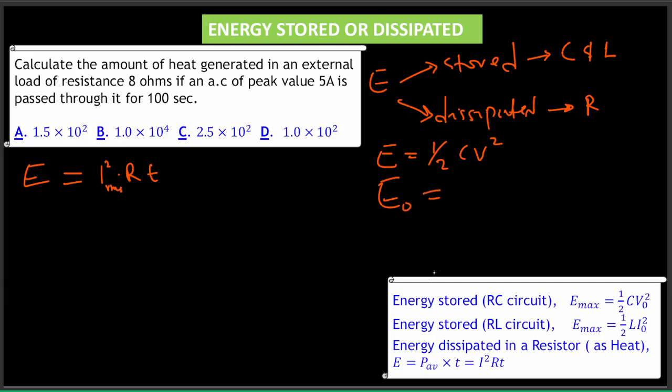All right, when you have a combined circuit, take a look at this. The maximum energy stored is half CV squared, but listen, V is the peak here. You can as well write it in terms of the root mean squared value. So half C, and then here you have the root mean squared value. That's V peak is equal to V RMS times root 2, squared like that.